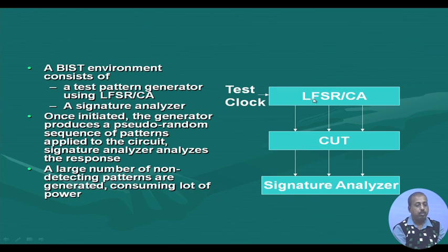Then the third pattern will be coming. That way, maybe after the first pattern, the 10th pattern generated by the LFSR detects some new faults. In between, patterns 2 to 9 are extraneous, and they are causing an increase in power consumption.